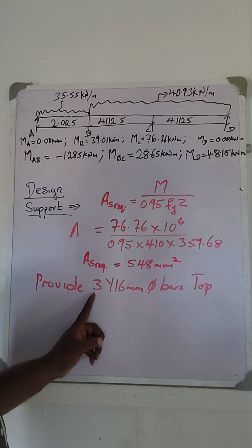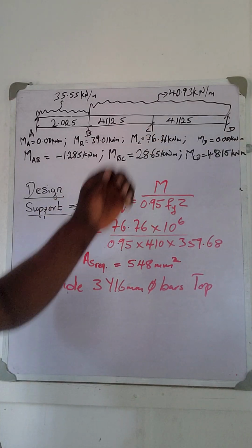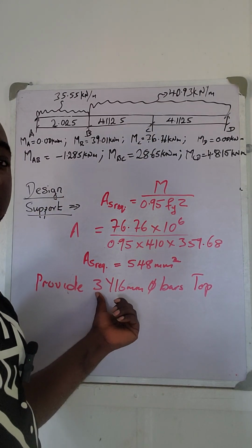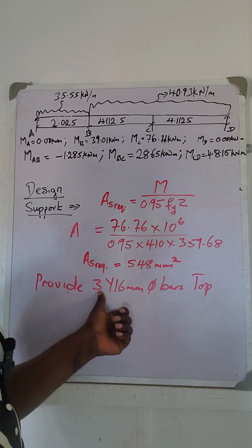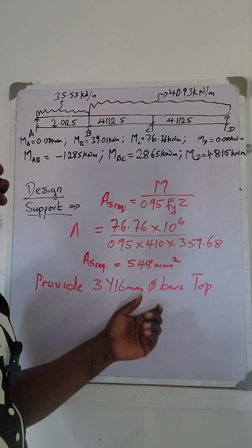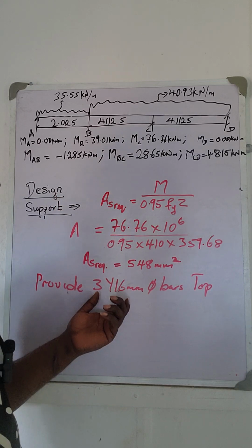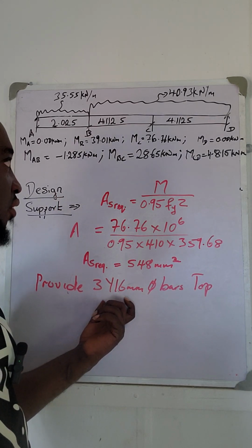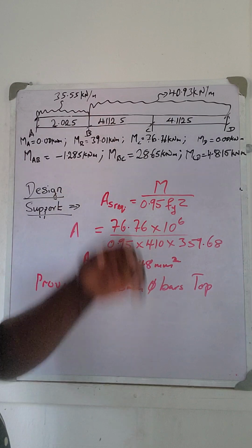This means that at this top level you provide 3 number of 16 mm. So you must analyze to know the reinforcement that will be adequate in the support.